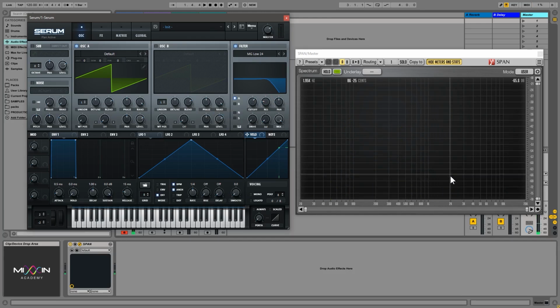This slope right here from 1K to 2K, which is 1 octave, double the frequency, we talked about that already in lessons past. So in that 1 octave, the volume is being cut down by 24 decibels. So each octave, 24 decibels down. And then up to 4K, again, another 24 decibels down, and so forth.